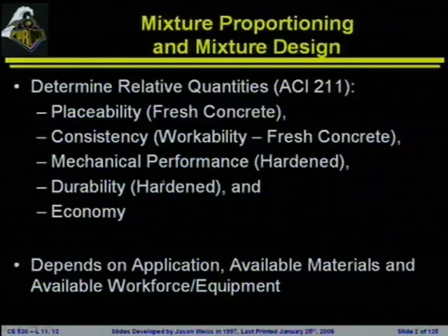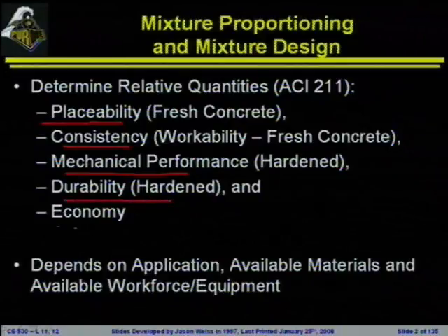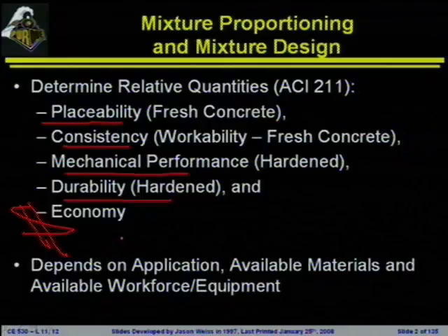Mixture proportioning, we'll talk a little bit about some of the details here. There are a few things that we really need to consider. Placeability of the fresh concrete is going to be one of the vital issues. Consistency in terms of quality control. Mechanical performance of the hardened concrete. Durability of the hardened concrete. And the biggest one that we're going to be excited about is really the economy of the overall mixture.